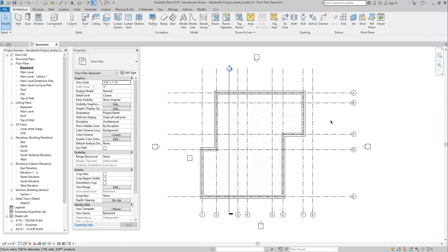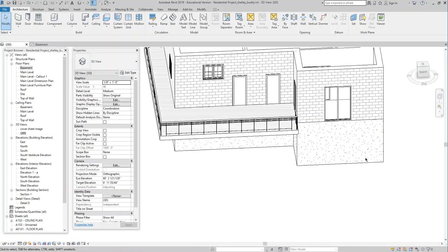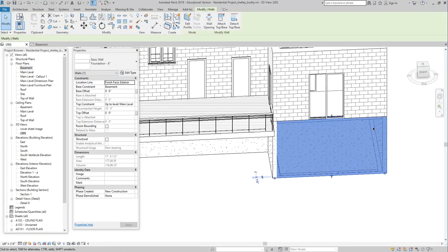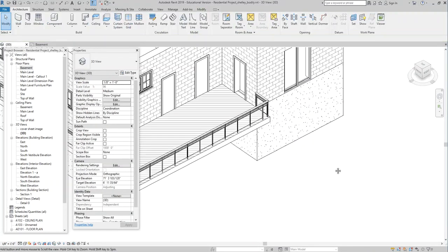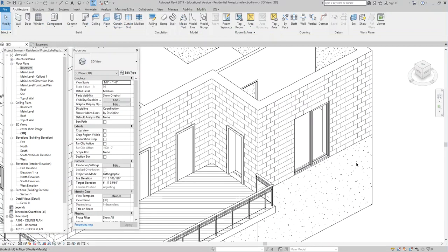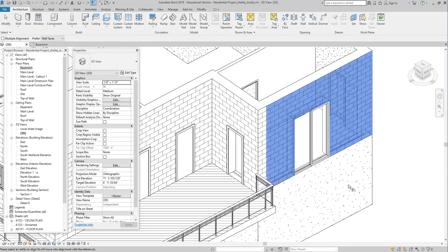It is. Yours is. So what you did, Gabriel, is when you created your walls, you probably created them to the center line of that wall, so it popped out a little. But what you'll have to do is what I was just doing: align, AL, and you click the top. You see that? Click the top, and then click the bottom face. See how that highlights? Click.